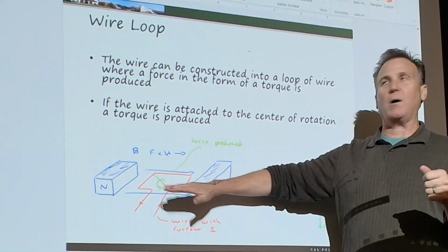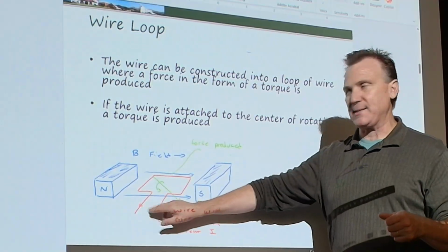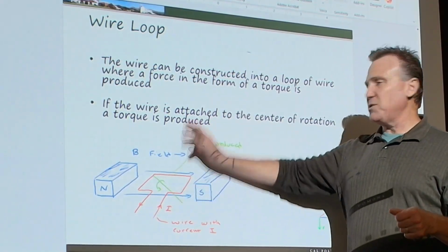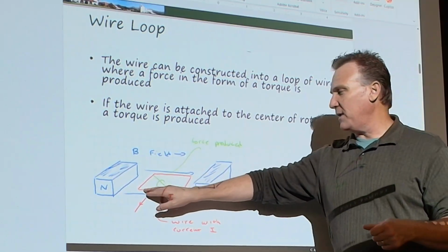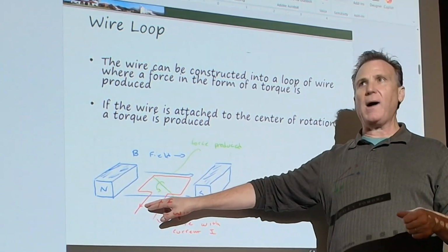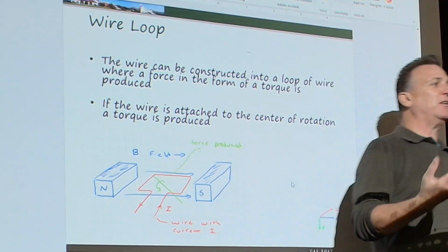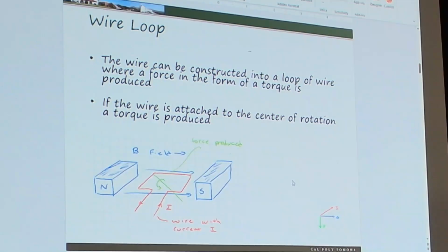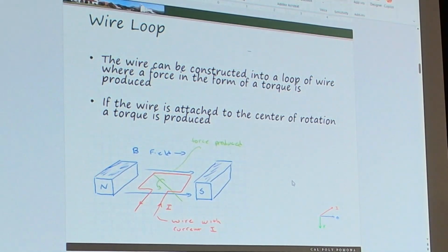all I have is I squared R, once I have that voltage. I'm looking at this as I squared R capacity. And this energy has to go somewhere. It's going to go into heat. And if I can't absorb the heat in that winding, the wire will break and melt. It will burn up. It turns into a resistor, a toaster element. Gets nice and red and goes poof. We burned up our motor. Literally, we burned up our windings.